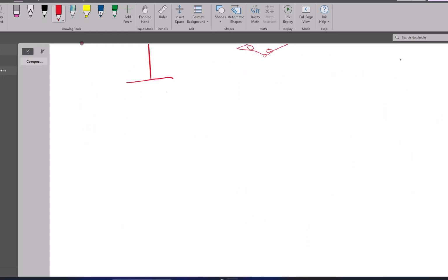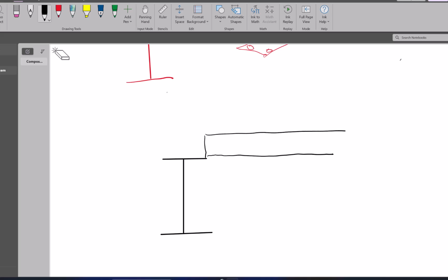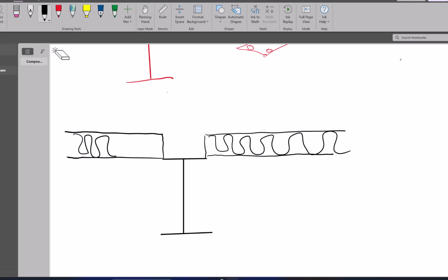What we have done in Pakistan for a while is the SCIP or ICF flooring system. How do we achieve a composite beam? It's simple. This is an I section, and we have our SCIP panel here. The details on that you can see in the link below. You have a SCIP panel here, and this is just the insulation material. This has no contribution whatsoever to the structural value. And then we pour concrete here.